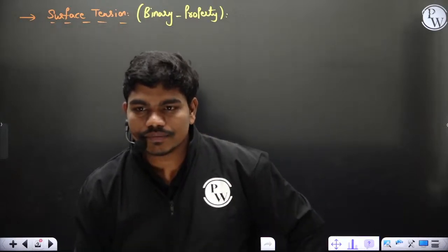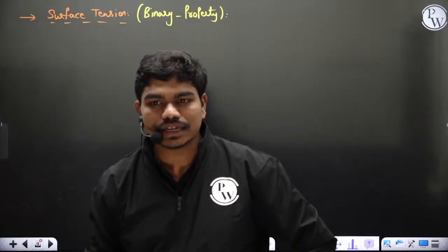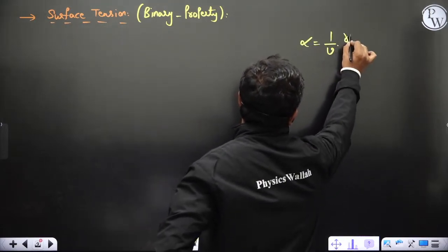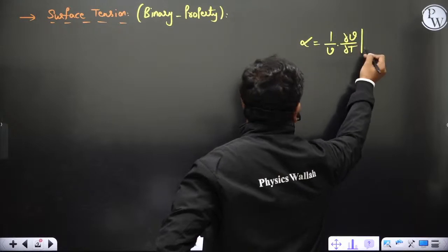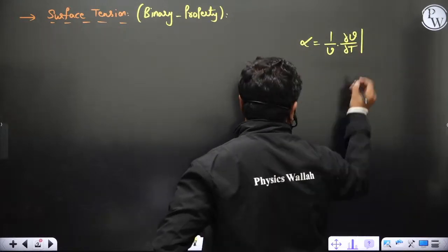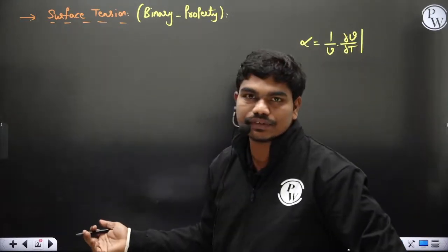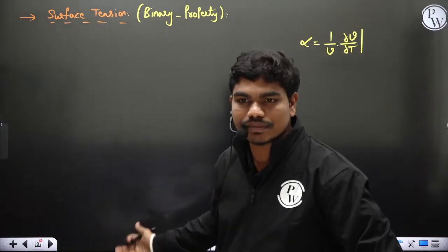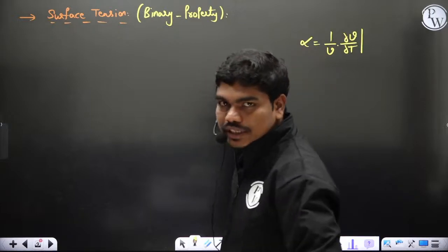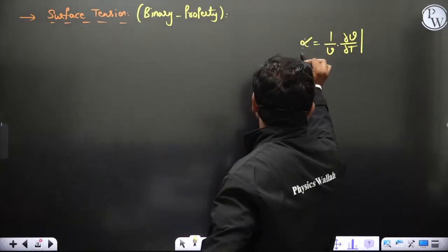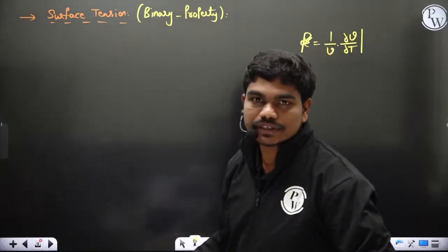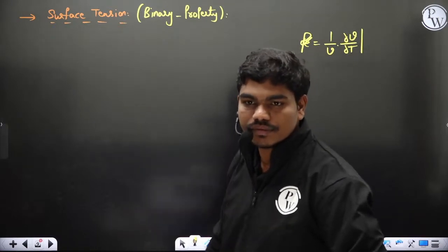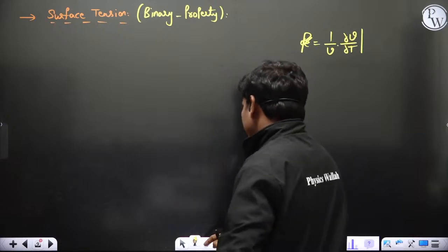Thermal expansivity will be seen better in thermodynamics. If you see, this is 1 by V dou V by dou T, depending on adiabatic conditions or isothermal conditions, you have isothermal expansivity or adiabatic expansivity, like compressibility. This is the expression for different substances, and you can calculate this value. In some books you denote it with beta also, volumetric expansivity. In the case of an ideal gas, this value comes out to be 1 by T. Fine, so we will see accordingly.